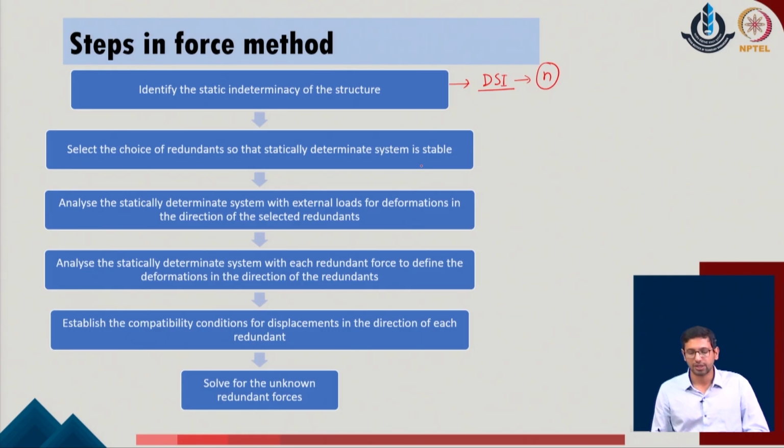So, by removing the unknown set of reactions of the given system, we convert the given problem into a statically determinate problem, and we call that a release structure. While we are defining the release structure, we have to ensure that it is stable, and at the same time we also understand that the release structure choices are not unique, and there could be multiple systems defined by different users.